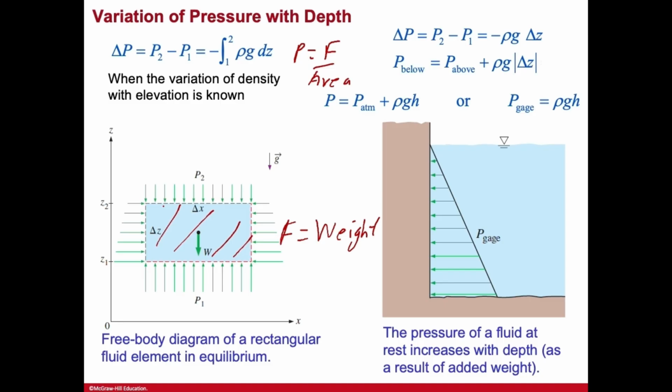So weight is nothing but density times gravity times the volume, which is delta z, which is this height, times delta x, times whatever this length is. Let's say it is delta y to make it even more general, right? So that is the force acting on this face.